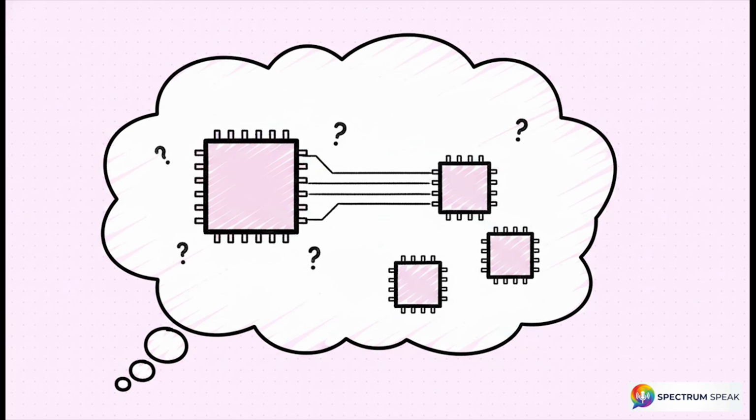Next up, Section 4, the controller gotcha. Before you take all this knowledge, grab a screwdriver and start tearing apart a circuit board looking for these exact chips, let's look at a major pitfall that constantly trips people up. Because we all learn from generic block diagrams showing three totally separate boxes, people mistakenly assume the CAN controller is always a separate physical chip on the circuit board, usually connected to the microcontroller by an SPI bus.